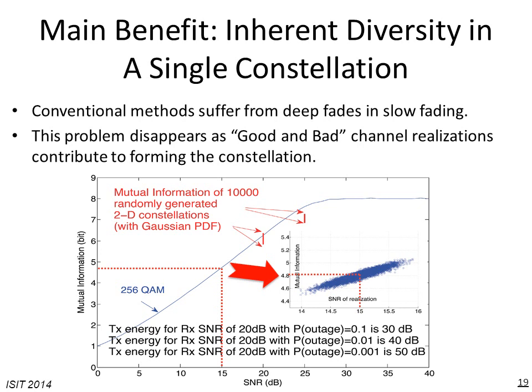The important point is that if we have a margin of about 1 dB or maybe less for this random signaling, we are sure that with high probability none of those 10,000 realizations will be in outage. So this gives an idea of what kind of margin for the signal to noise ratio we need to avoid outage. This margin shrinks to 0 as the constellation size increases.